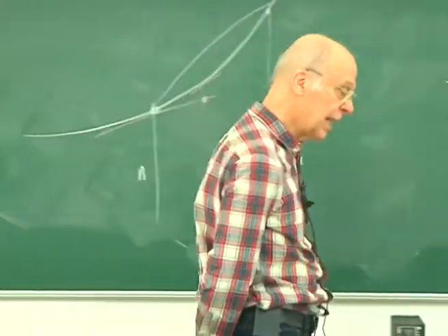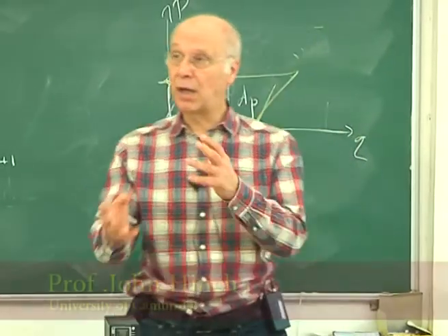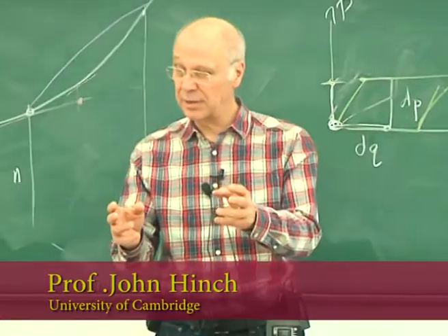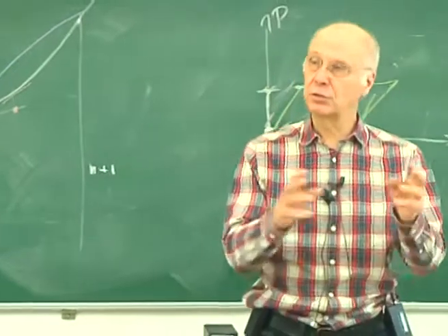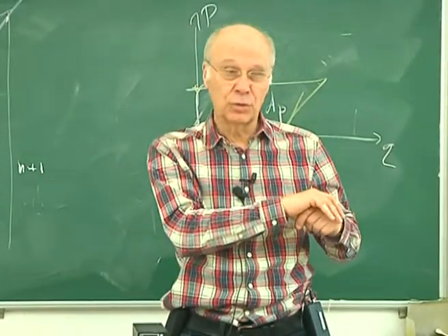Right, so then there's how do you deal with pressure. I mean, it's done by a half-step method, a split time step method. You make a time step with no pressure, and then you do the time step with the pressure. But this is doing it to second order accuracy.